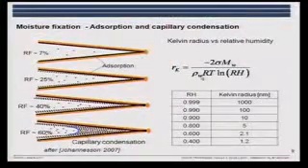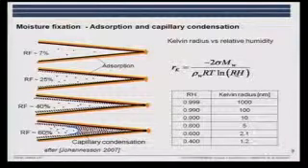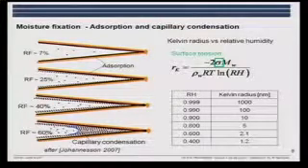The numbers here: we have the molecular weight, the density, the gas constant, temperature, and the relative humidity. And you will see that sometimes we change the surface tension of the pore liquid on purpose, and we get a different water content, and we also have different stresses being set up in the pore structure, because when we start to have the meniscus, stresses are set up, and we can change these stresses by changing the surface tension. This is shrinkage-reducing admixtures, and I'll not talk more about that today.